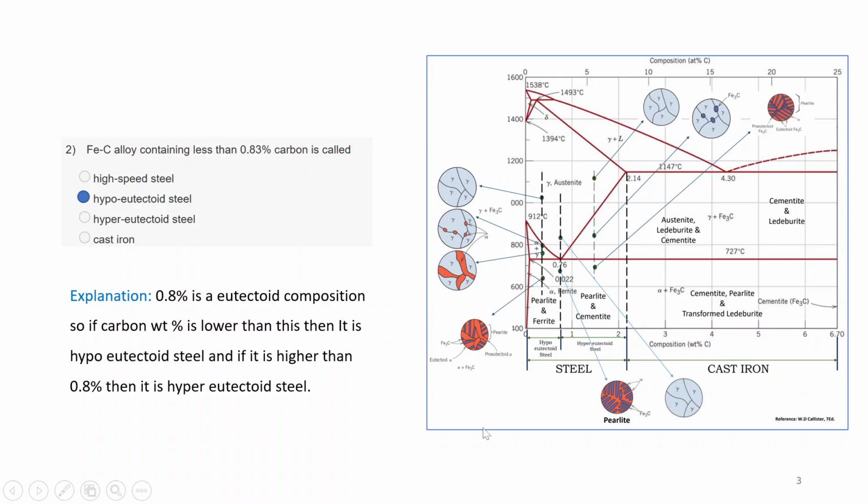And another thing, ma'am, which material possesses which property, or which ingredient, if we add it, which type of strength is increased. They are quite similar, a little different. That is a little tricky thing to remember. You should remember what the difference is between them. For example, you remember cobalt for high temperature. You need to make notes so that you can remember those. Vanadium for grain refinement, and the others will be similar.